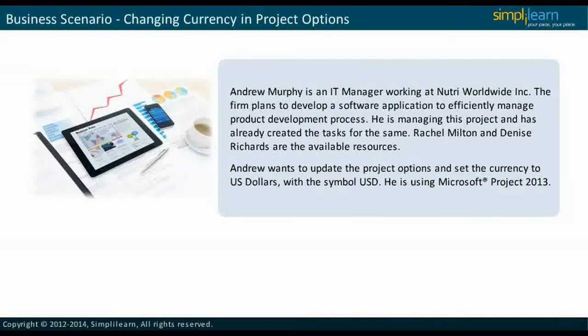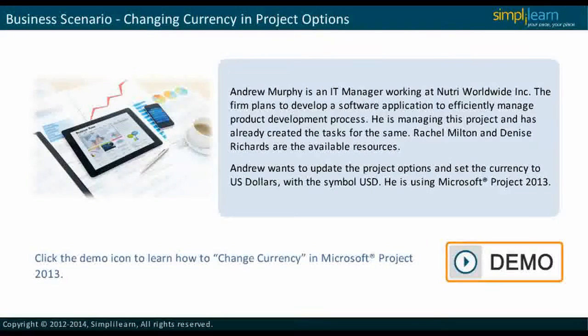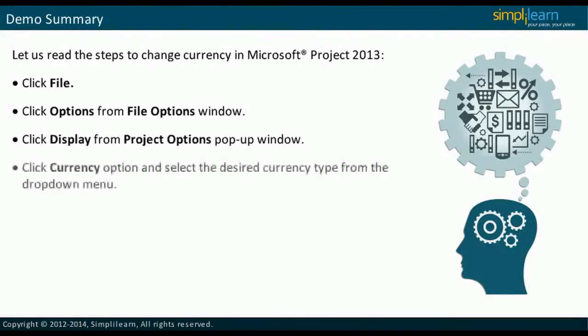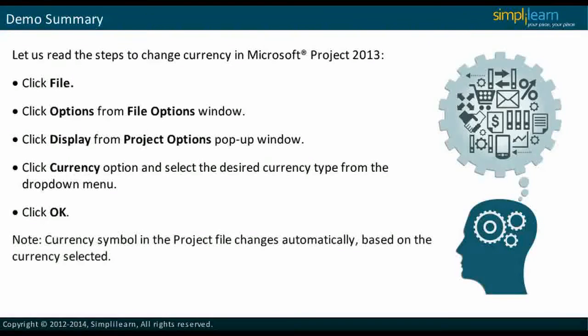Andrew wants to update the project options and set the currency to US dollars with the symbol USD. He is using Microsoft Project 2013. Click the demo icon to learn how Andrew changes currency in Microsoft Project 2013. Let us read the steps to change currency in Microsoft Project 2013.